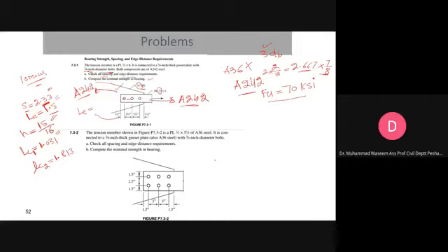Okay, I think the time is up now. Rn, for this case over here to this side, the controlling bearing strength is 32.48 kips, and in between you have Rn, which is 55.12 kip. Okay, so there are two problems.